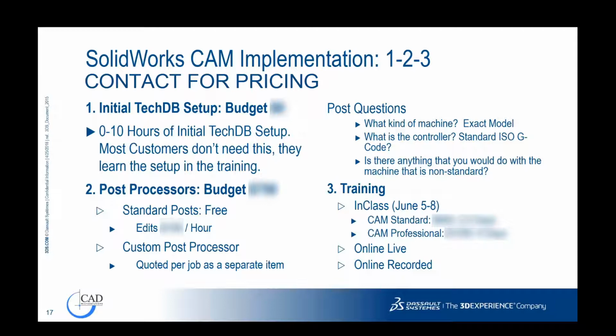Yes, you're going to need post-processors. There's a series of post-processors that come for free with SolidWorks CAM. But again, considering the investment in capital and how good the post-processors that CAMS has, I would budget a little bit of money if you're thinking about implementing SolidWorks CAM for getting one of the professional quality post-processors that CAMS has. The type of questions that we're going to ask you are what kind of machine it is, what kind of controller, and is there anything non-standard that you're machining, and we can help you with that.